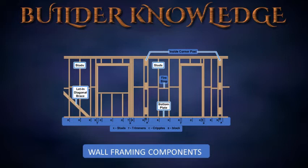Next, let's cover studs. There are different names and purposes for studs. The common studs run from sole plate, also known as the bottom plate, to the top plate. The trimmer studs actually are used to trim all door and window openings. The cripple studs are studs placed below a window sill or above a header. And last are the king studs.